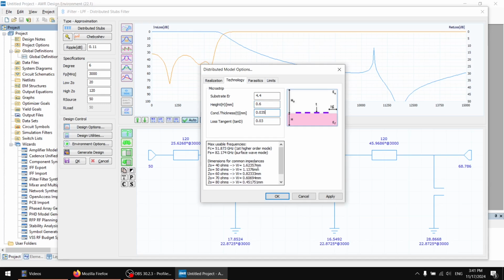So this is something that I have at home that I can etch using some chemical solutions. So I will stay with this 0.6, but if you are ordering PCBs, check that this option is not prohibitively expensive, because it might be. From JLC, I've ordered PCBs that were 1.2 millimeters. So I will keep it at 0.6 because I think I will be able to demonstrate something.